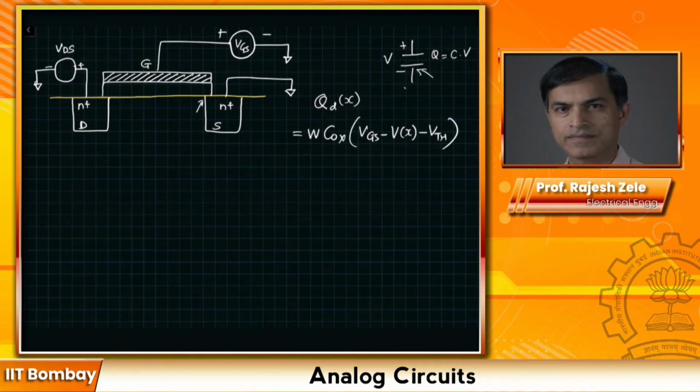So in the case of MOSFET, Q is given by C times (V minus VTH). And I think once you understand this part, the rest of the things will fall in place. And that's where this minus VTH comes in. However, the voltage at the channel, if we look at the different points in the channel, I'm going to show you different arrows. The first arrow, what is the channel voltage, is going to be VGS minus VTH. And the channel voltage at this point is going to be VDS because we are at the drain region.